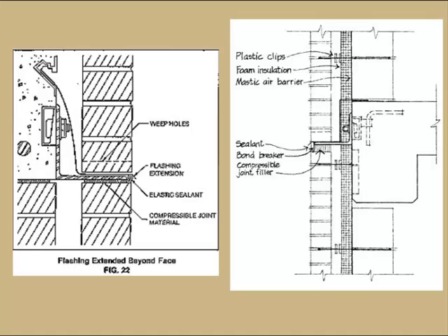Well, as you said, a lot of materials have been used in the past, anything from bitumen-type materials to tar papers to plastic sheeting. But what really works best are the materials that we know have long life to them, which typically is going to be the non-corrosive type metals. A backup flexible membrane over the top of them is always still a good idea, but the base flashing would be typically a stainless steel or a copper flashing. Okay.